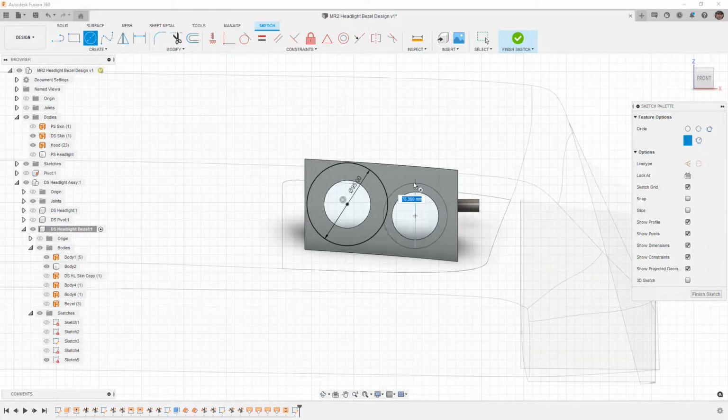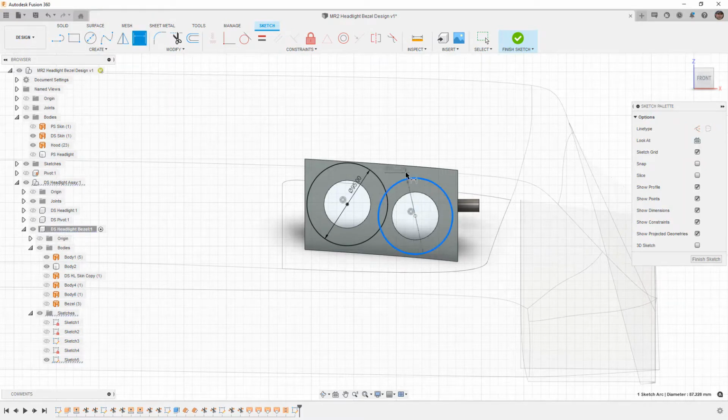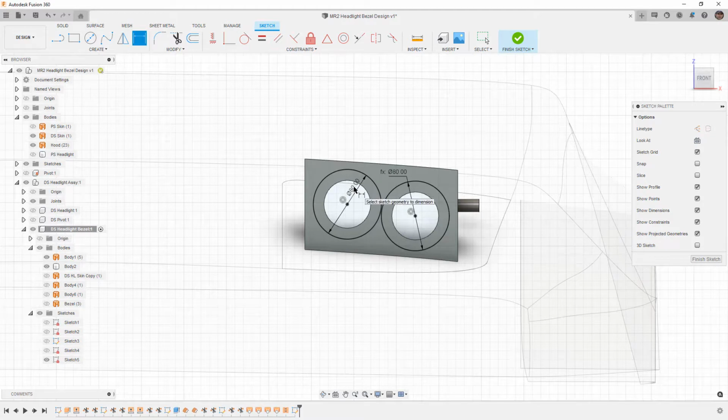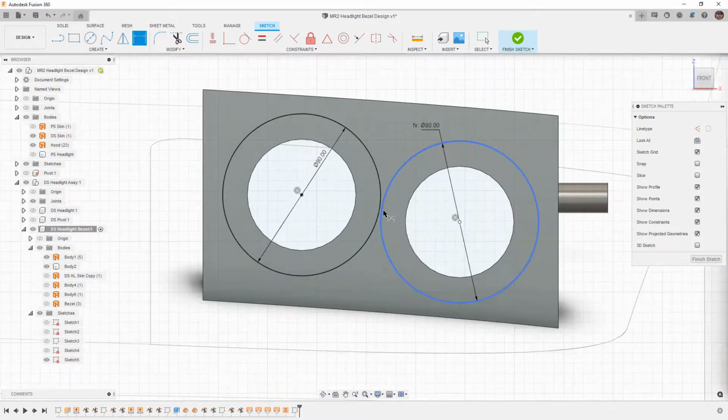So this is going to be tricky because these two are likely going to overlap, and we need to decide if we want them to overlap or not. So I'm going to make the dimensions the same, and then I'm going to play with these dimensions until they don't overlap. So let's try 85. Gets us pretty close. 80 is the magic spot where they don't overlap.